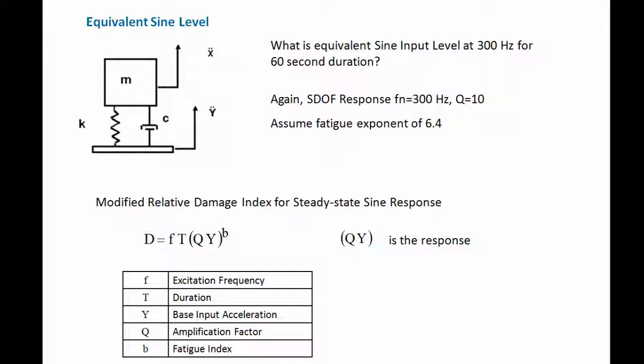Now, is fatigue the only failure mode? No, it's not the only possible failure mode. We could, for example, have loss of clearance, loss of sway space, loss of alignment, mechanical interference, and each one of those would be a relative displacement type of failure mode. And there are others as well. Some systems will fail if the acceleration reaches a certain peak threshold.